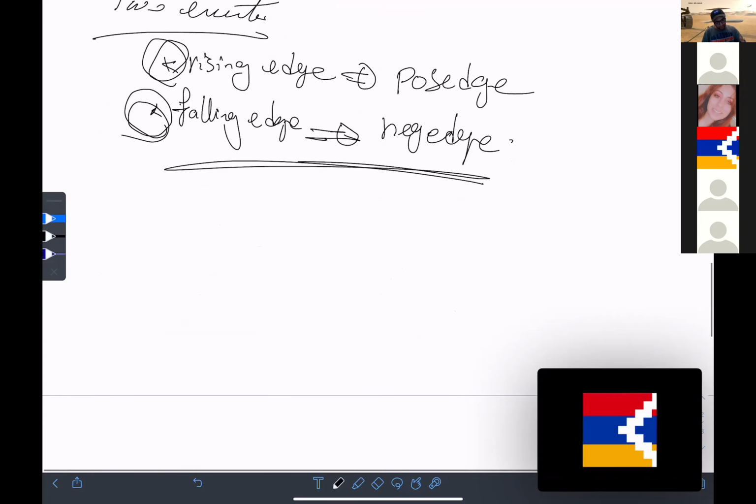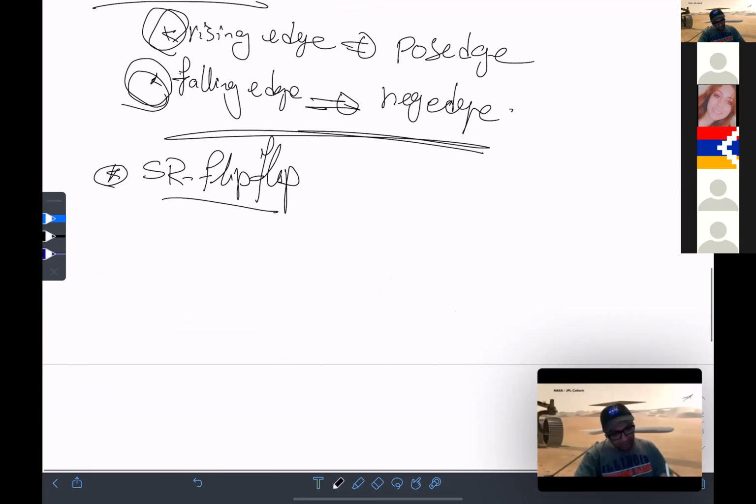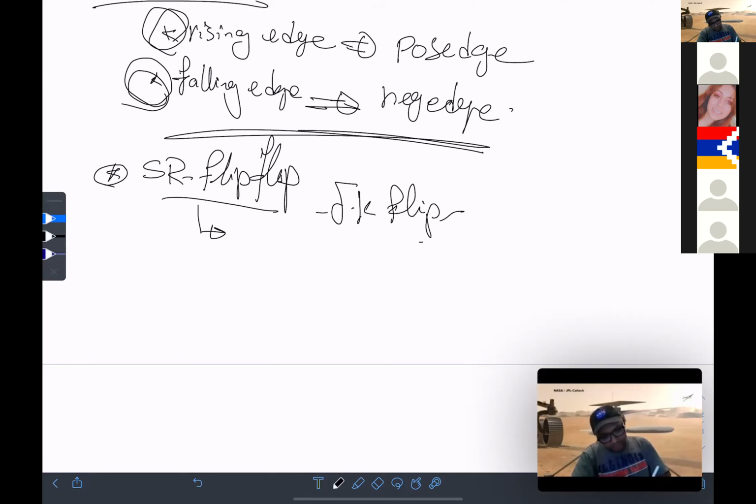Okay. Anyway, historically, they built the SR flip-flop out of the latch, right? Then they found out that the state table, the truth table, is missing one state. There is a state that is not usable, right? Then they tried to build the JK flip-flop to solve the SR problem, but it actually created a new problem, which is called toggling. That means the state continuously flips the data back and forth, 1 and 0, 1 and 0, 1 0, 1 0.